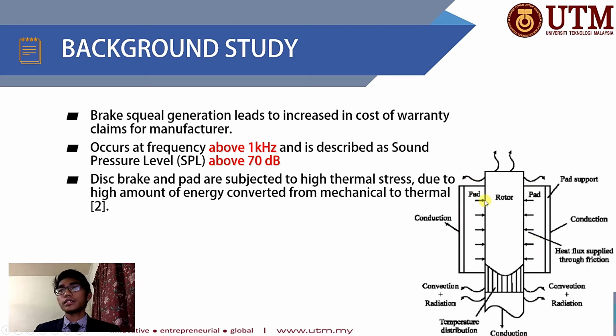As you can see, heat is generated from the pad to the disc rotor and dissipated through the lining of the disc rotor. Convection and radiation happen on the surface of the disc rotor.